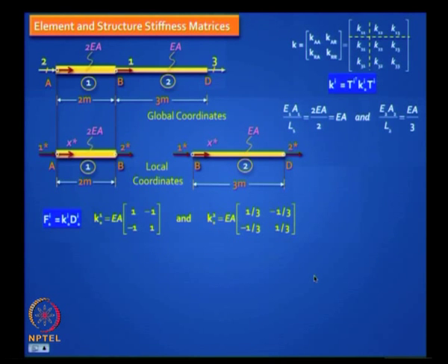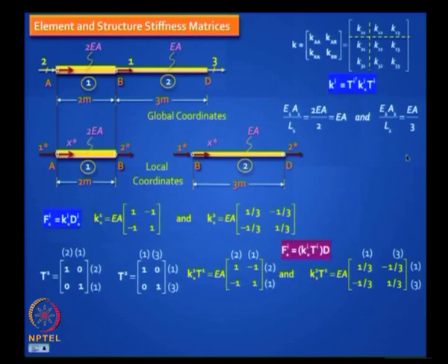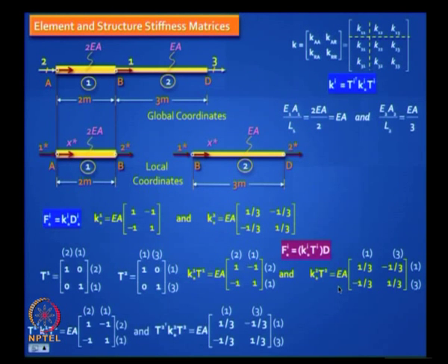Then you do the transformation, you have T1, T2. You need to do this, but it is better to do this first, because you will need this to get the internal forces. So do this, which is actually very easy because you are multiplying with identity matrix, but now you are putting the linking coordinates, and again you multiply with T1 transpose, you will get that. So finally you have got these values.